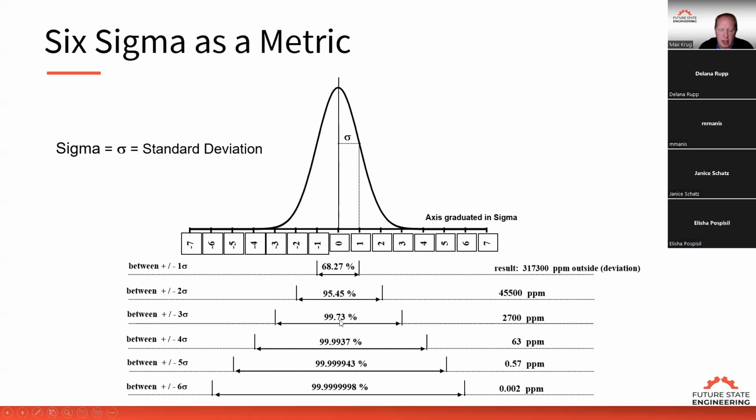So if I take that 0.27 and divide it by 2, because I've got a 2-sided histogram here, that gives me 0.135%. So there's a 0.135% chance I'm going to get a point outside the limit if it's operating normally, which is very, very small. That's 2,700 parts per million. So if I run 1 million parts, I only expect 2,700 of them to be outside one of the limits.